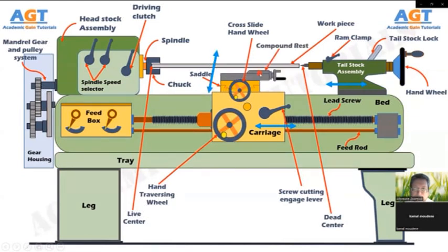Above the cross-slide and saddle, the compound rest is mounted. The compound rest supports the tool post and cutting tool in its various positions. It can be swiveled at any desired position in the horizontal plane. Compound rest is necessary for turning angles and boring short tapers. It can rotate and fix to any desired angle. The compound rest slide is actuated by a screw, which rotates in a nut fixed to the saddle.